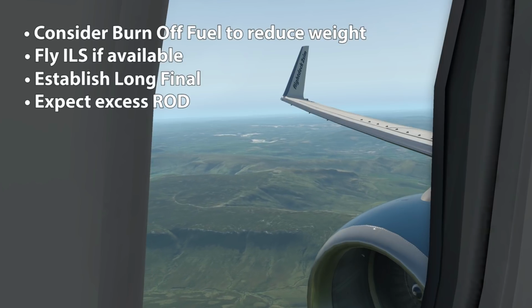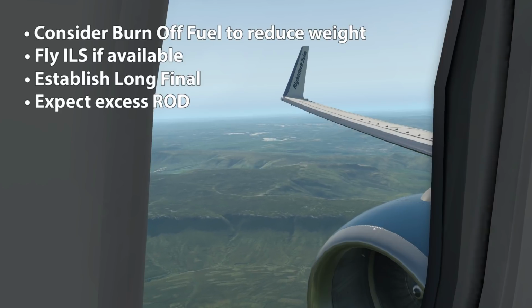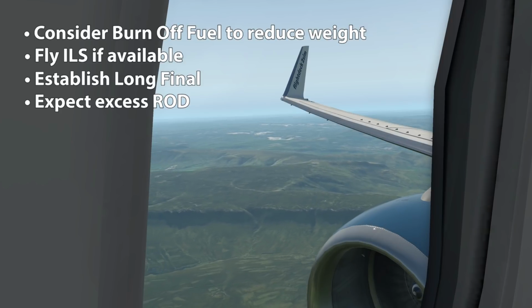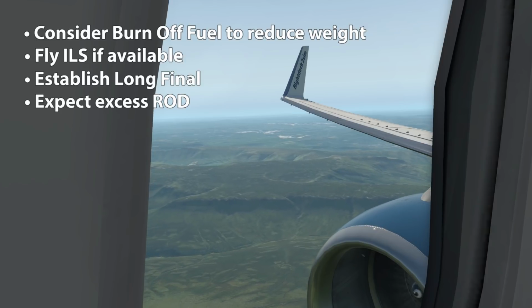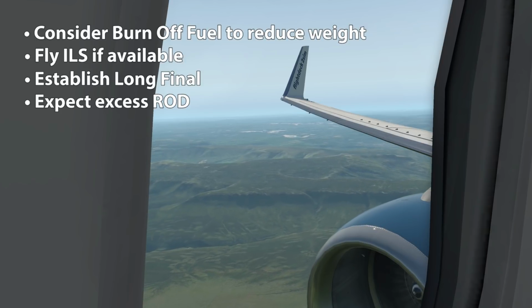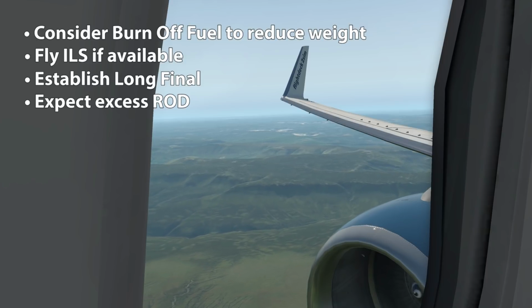It says expect excessive rate of descent and lower thrust on final approach. So typically at the landing gates, we need to be ensuring the rate of descent is not in excess of 1,000 feet per minute. It will be in excess of that today. So we would brief that to pilot monitoring. That would be the normal case in this situation.